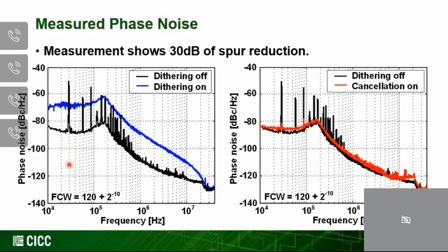Okay, so here I'd like to show you some measurement results, and you can see that when I turn off and turn on the dithers, if I do the turning on and without cancellation, you see the noise floor will go up, but the spurious tone will go away. Right? So this is where we do the phase modulation on the quantization errors, but I still have that dither signals. So then later on, we can further cancel out that dither.